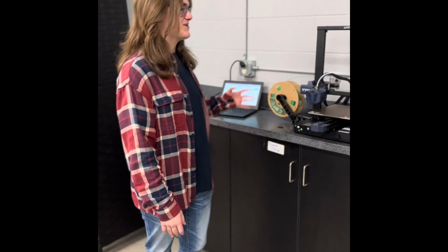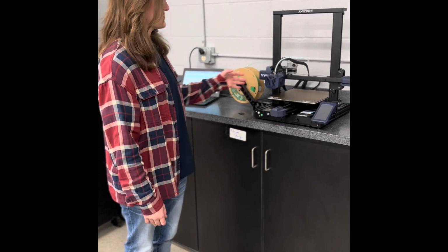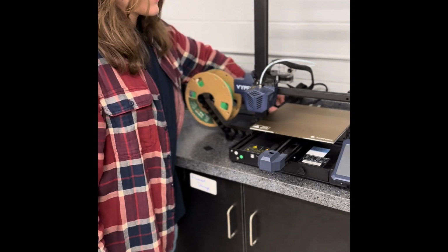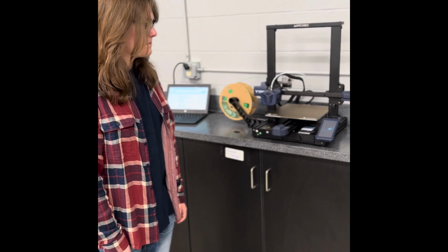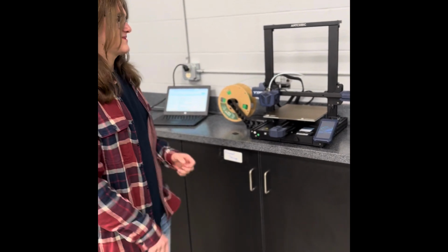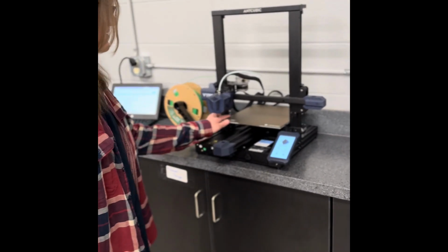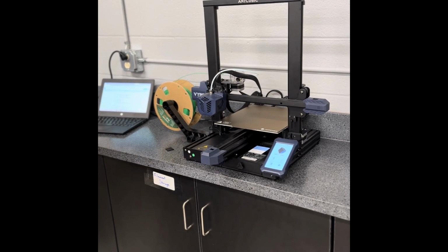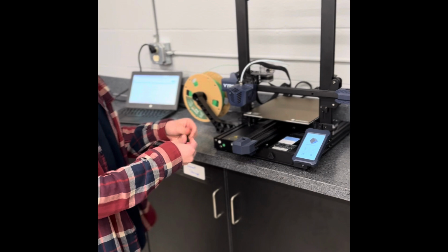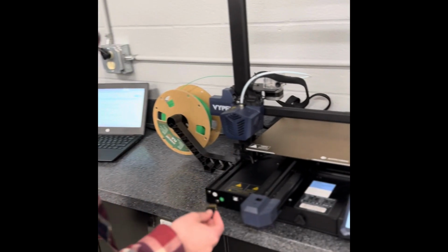Okay, so on to the printing step. First, you're going to want to turn it on. As you can see here, this is where the power button is on the back. So I'm going to go ahead and reach around, turn it on. And you'll want to give it a second because it takes a second to kick on. And then you'll want to make sure this is pushed all the way back. And you take the SD card, make sure it's on this side where the gold lines are, put it in.